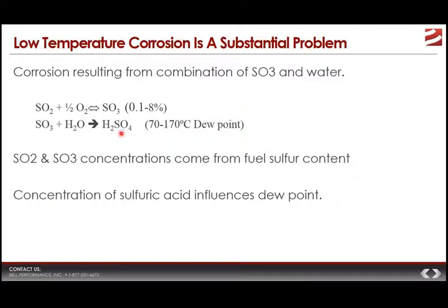The operator thus has a problem. He or she's got multiple problems, really. They want to maximize their efficiency, right? They want to get as close to maximum efficiency as possible, but they also know that they're probably going to have to sacrifice some of that efficiency in order to solve both hot temperature and cold temperature corrosion and keep those from happening, because they want efficiency, but they do not want corrosion. So what are their options?